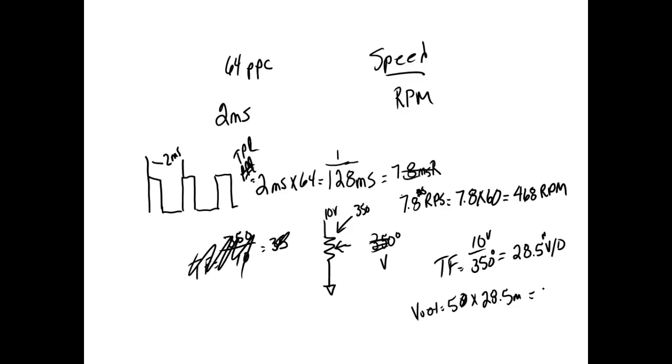An incremental encoder, to get speed, has got to count these things, right? So in the PLC it would be a lot easier. We don't deal with time, we deal with the number of counts. So if I can count these pulses for 1 second, and then take that count and multiply it by 60, then I got RPM. So PLC programming is a little easier. We use this example because this is the one they use on the Siemens level 1 test.